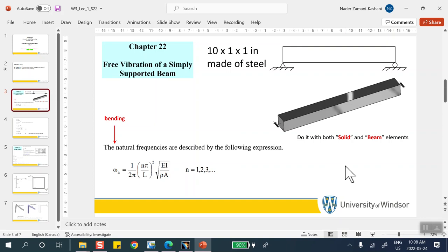dynamic load, now dynamic load means, for example, your fan is sitting up here, it's turning because of the unbalance, this guy starts moving. This is not free vibration. It's vibrating because of that fan. It's not that I move this thing up and let it go. That's free vibration. If you have a unit sitting up here that causes this thing to go up and down, not in the same shape as the first mode or second mode, all of these are going to be in it, okay?